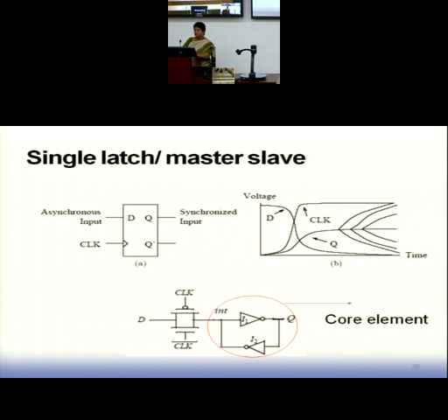But do we have time to wait that long? We cannot allow that in my D flip-flop, because I only have one clock cycle. Within one clock cycle, either you give me the input or you leave the input, because otherwise the system cannot keep on waiting. Either you latch in the data or you don't. You take a decision immediately, but you have only one clock cycle available. So we have to find one clock cycle solutions.